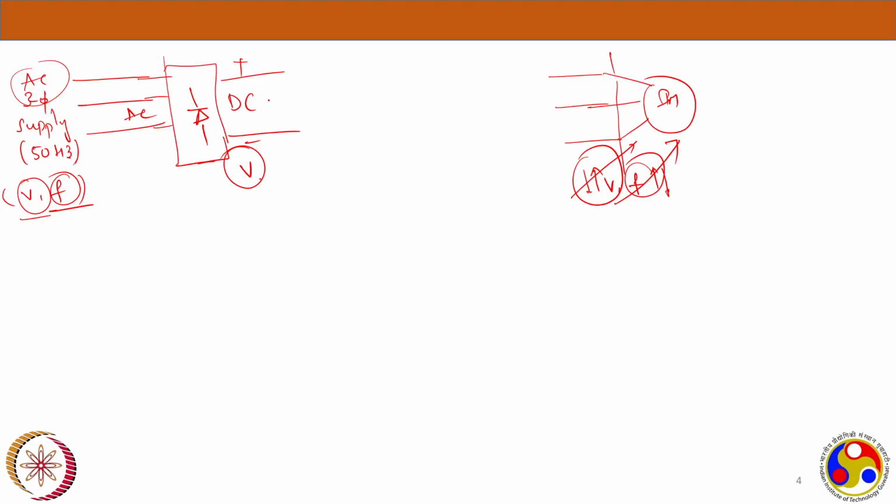So what I would do, I would connect simply a, and also of course this is DC, of course this is AC. We would like to have an inverter in between. Okay. So this three-phase inverter, what does an inverter do? It will convert DC to AC. Now again I will be left with AC, and my motive is what? To get a variable frequency and also variable voltage.